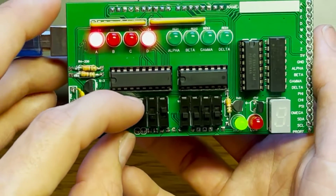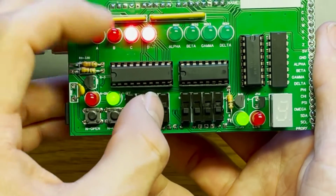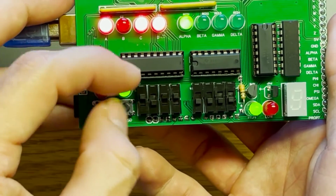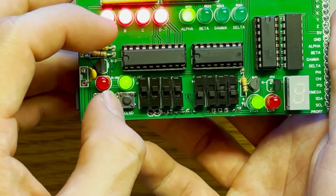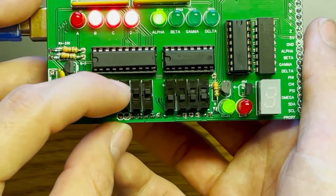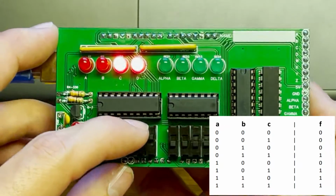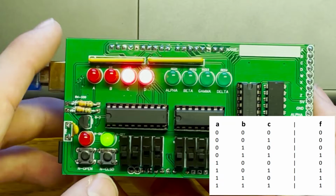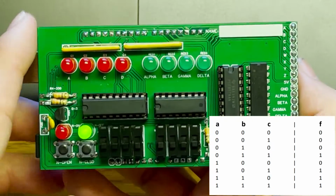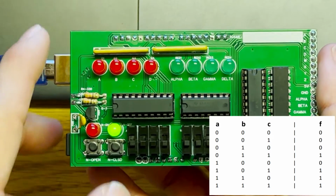I have A on, the rest is off. I'll turn on B, B off, C. All right, C is on, I'll turn A and C on. The light turns on. Turn A, B, C on. Have B, C. If I have just 1 on, then the light turns off. And this is shown in the truth table right here on the screen. As we can see, alpha only turns on when at least two 1s are present on the truth table.